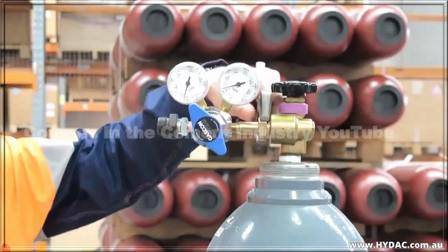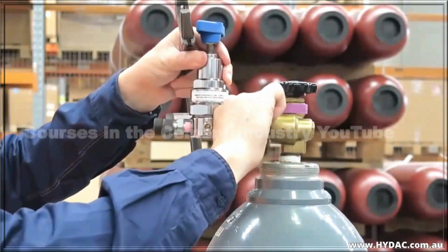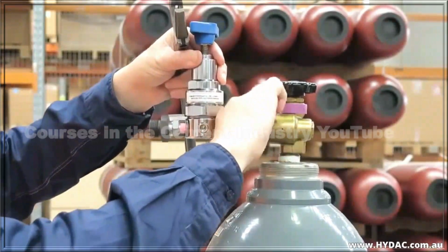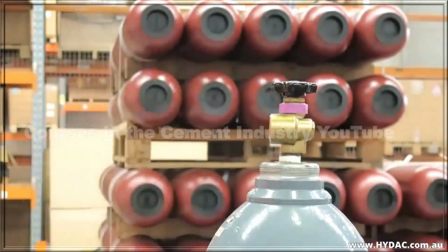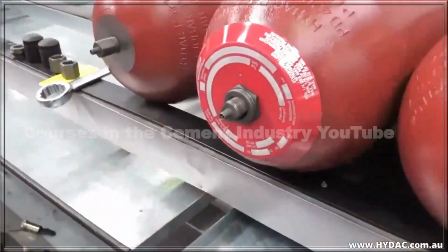We recommend that the gas pre-charge pressure is rechecked the following week. If there is no gas loss observed, check again after 4 months. Again, if there are no losses observed, a 6-monthly inspection cycle should be sufficient.